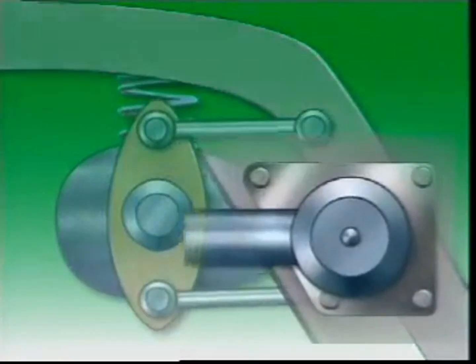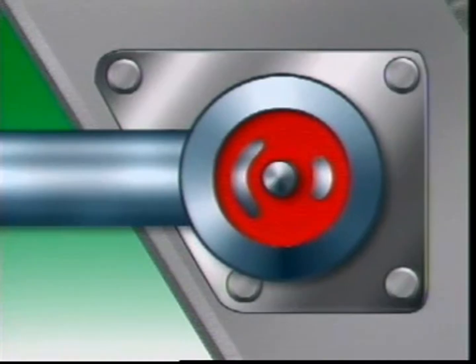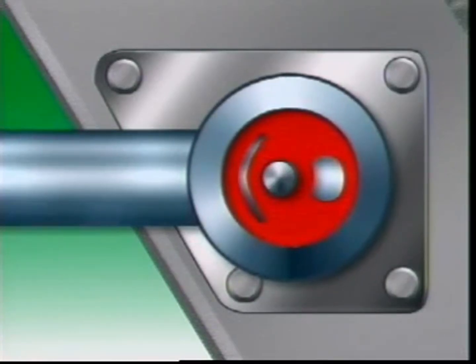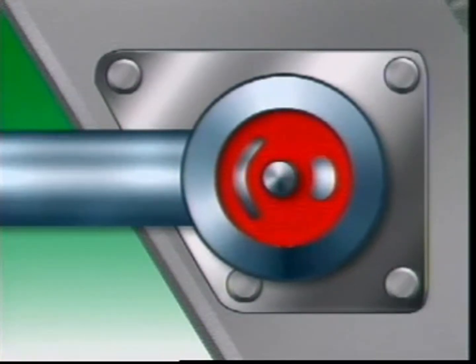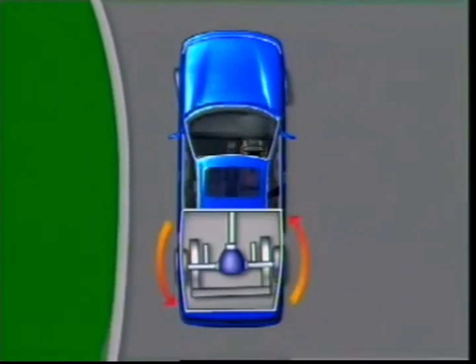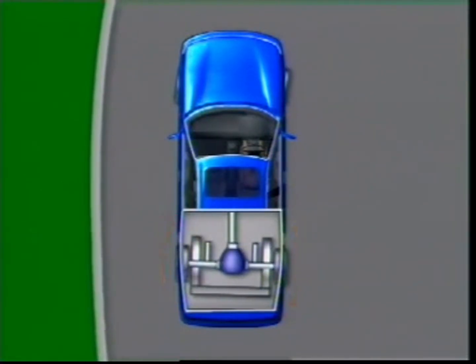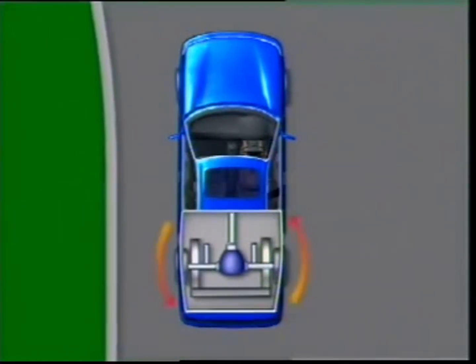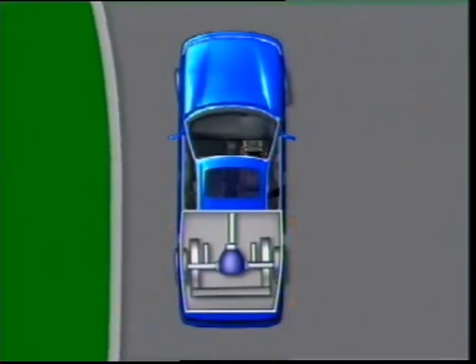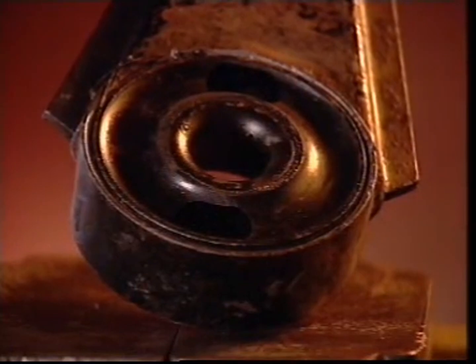In control arm applications, particularly at the rear of a vehicle, the rubber arm may be molded with a voided section. This is known as a compliance bush because it allows the unit or component to comply with a controlled amount of movement in the direction of the void. This movement relative to the vehicle frame allows compliance or deflection steer of the road wheels when cornering. Since this influences the steering behavior of the vehicle, it is very important the voided section is in its correct relative position.